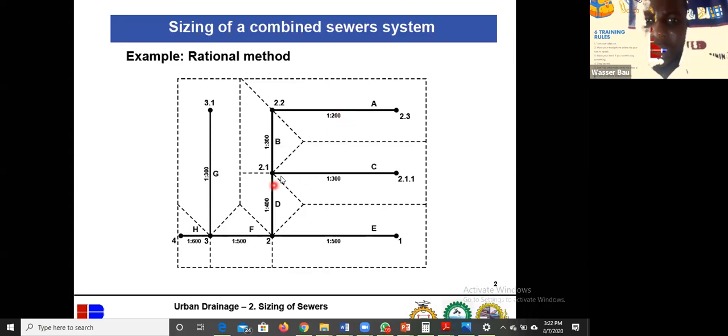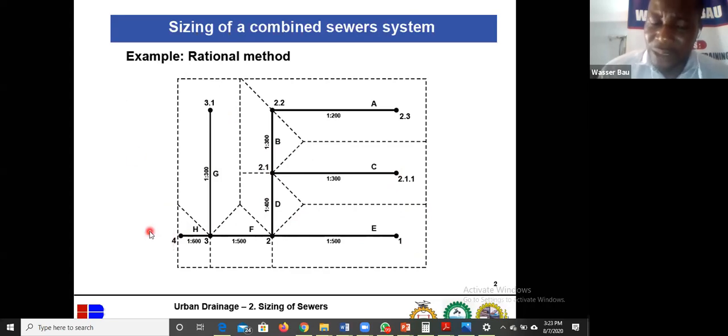So in this study, we are assuming that at point 4, that is where you have your outfall. This is where you have your outfall. Okay, and so here are houses that will drain, and then when it gets here, the catchment B or Wuse or Lekki will join it. When it gets here, Aja or Buzape will join it. So what you see here are really big units. And then at the end of the day, they will go to either here, which now becomes the treatment plant if you are designing for sewer, or becomes a water body, an outfall, if you are designing for stormwater.